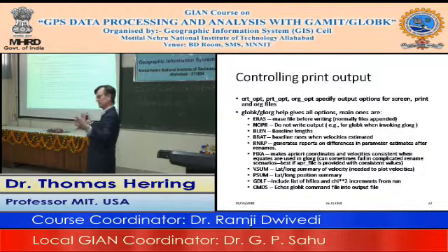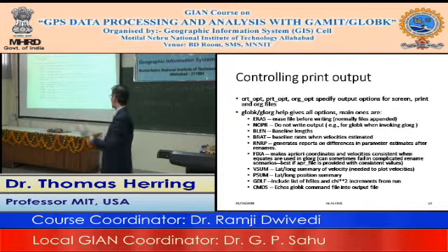And again, if you're doing a very large solution and you want to make sure it gets through, and you might potentially have a bad H file in there which has some station that's just really weird, then you might want to stop it incrementing anything more than 10, or maybe even 3 or something like that. Depending on what you're doing, it will tell you what that increment was, and you can limit it so it doesn't get added in. Or if you put this output, it'll have a used or a not used at the end of the line to tell you whether it was actually used.